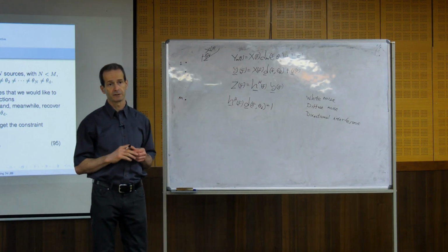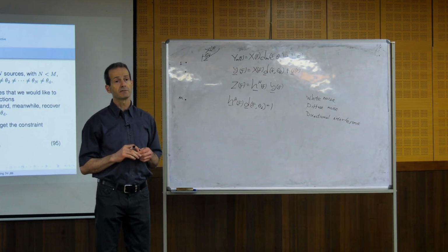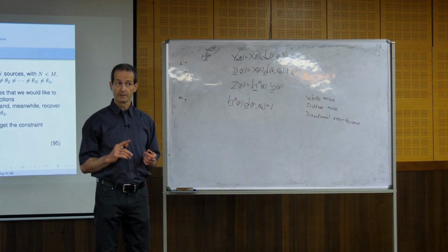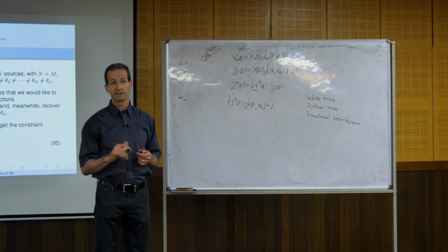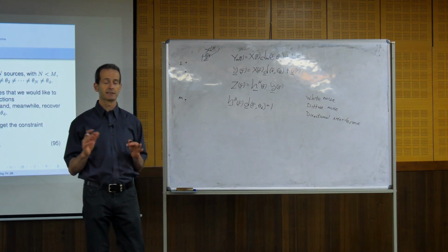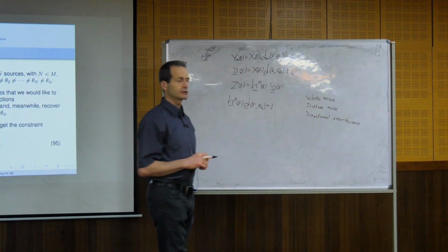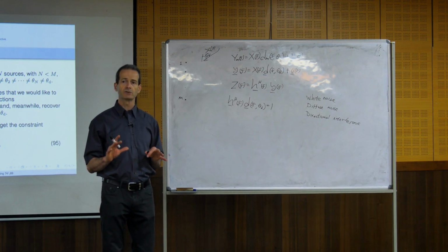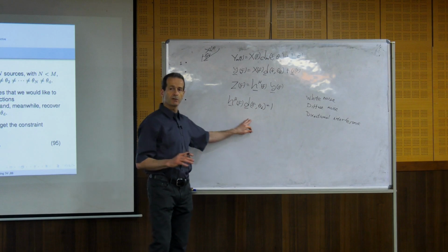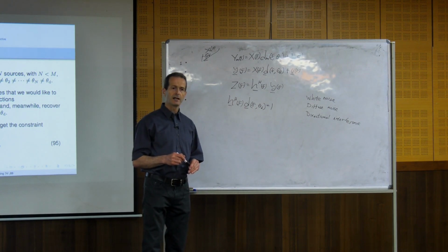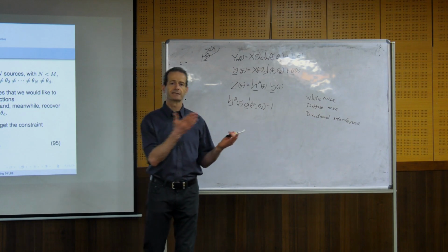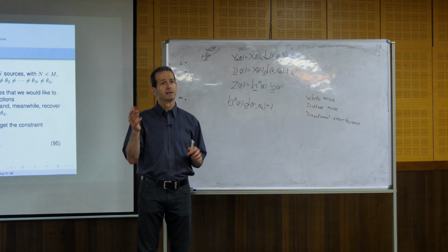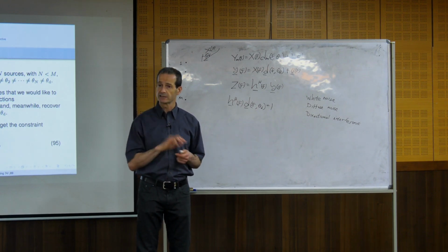This is very important. You see, for example, when we talked about multi-channel signal enhancement, of course also single channel, but I want to limit ourselves to multi-channel, we don't necessarily use a constraint of distortionless response because we try to find a trade-off between signal distortion and noise reduction. So sometimes we try to reduce more noise and we allow for some distortion of the desired signal.